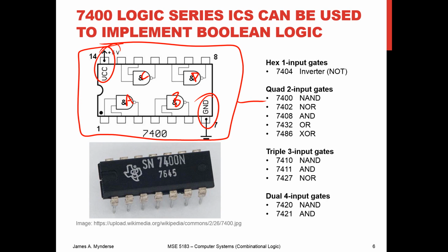And so for the first one, it'll take inputs X and Y and give output Z. And so Z will be X and Y NANDed. And you've got 4 of them in this package. You can get similar sorts of 3-input gates. You can get 4-input gates, and it's just a standardized set of parts. It's called the 7400 logic series.